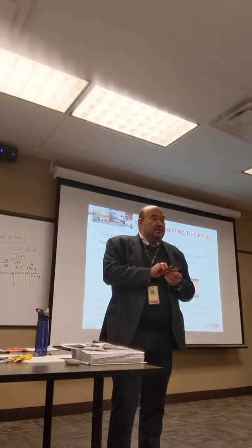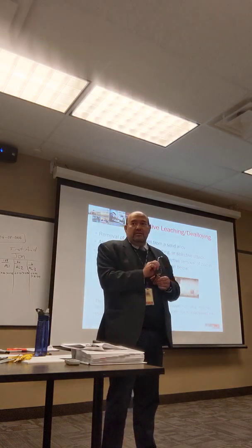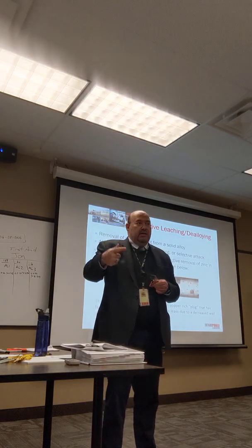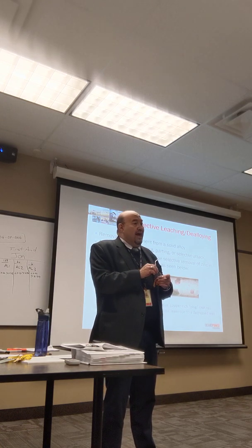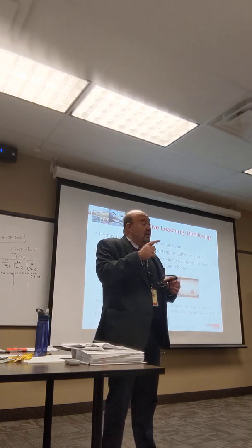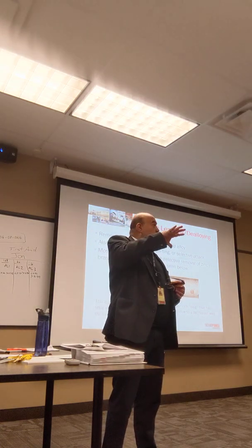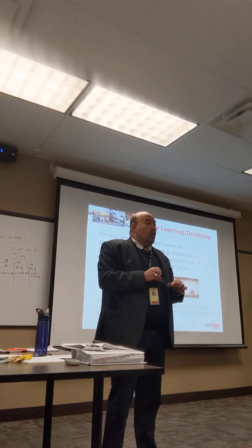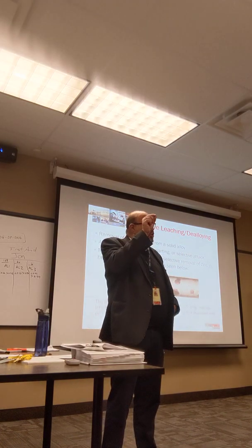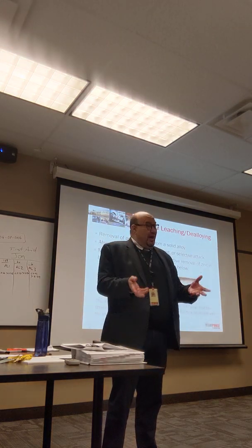Yeah, so this is one of the conditions that's happening, and part of the mechanism for that is galvanic corrosion, or a micro galvanic cell that is happening. So it's either with the global microstructure, or locally, that's causing some components, or elements, to disappear.